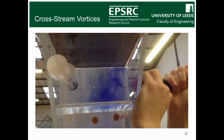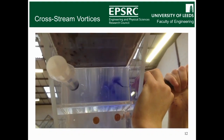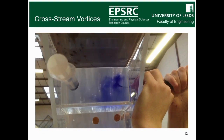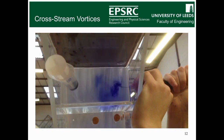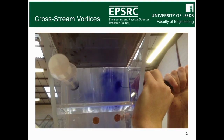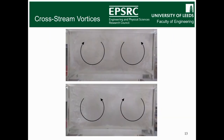Right, so in this video, it's a bit slow, but I don't know if you can see, there's some dye being injected into one of the step cavities. And the dye seems to be restricted to half of the channel width, but it also seems to circulate in an anti-clockwise direction. And what you actually see is that at each step there are 2 vortices, which I've named cross-stream vortices to distinguish them from the recirculating vortices I talked about before, going in opposite directions and meeting at the center line. But what's unusual is that the direction of circulation of these vortices changes at each consecutive step.